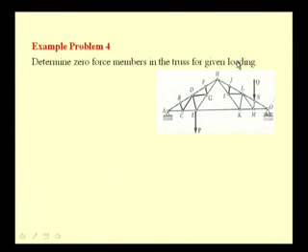Here we see a plain truss which is connected by a pin joint at A and a roller joint at O, and some external forces P and Q are applied at joints E and N. The problem is statically determinate because we have only three reaction components to be determined, and from the free body diagram of the entire truss it is possible to determine the same.